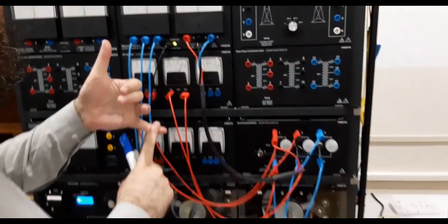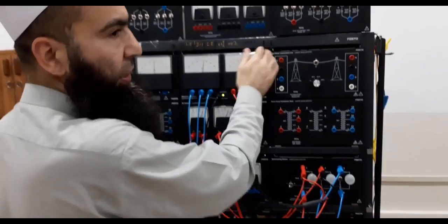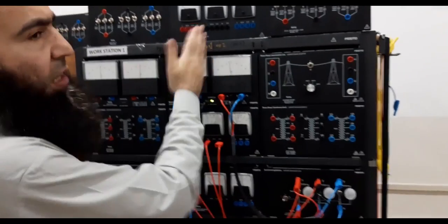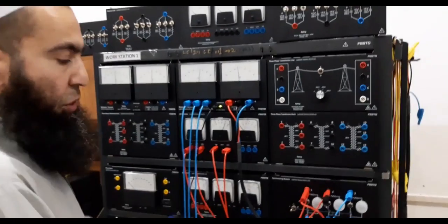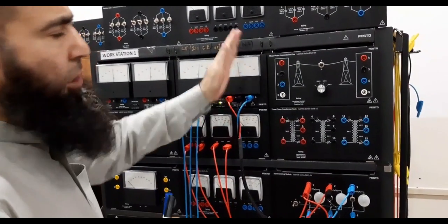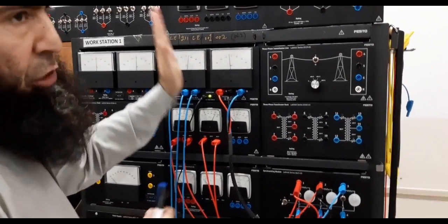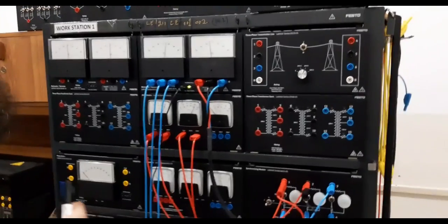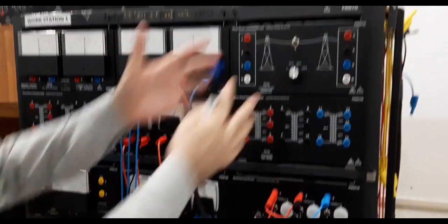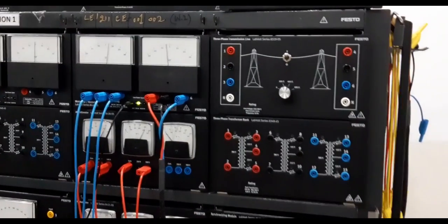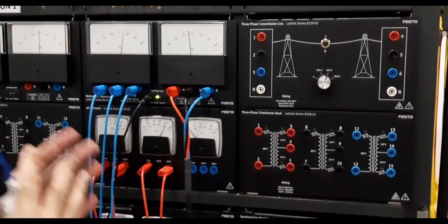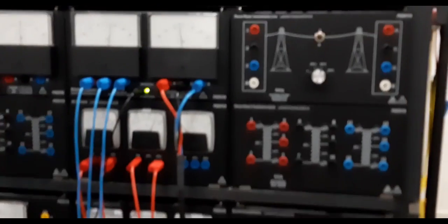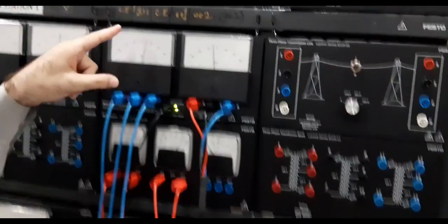We initially changed the field current, and I demonstrated to you that the reactive power changes. There is hardly any change in the active power. And if we change the prime mover power, the reactive power is more or less the same, only the active power changes. If we remove the prime mover by reducing the DC voltage to 0, then the system provides active power to the machine, and it no more acts as a generator, rather it acts as a motor.